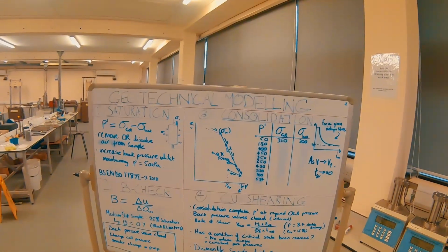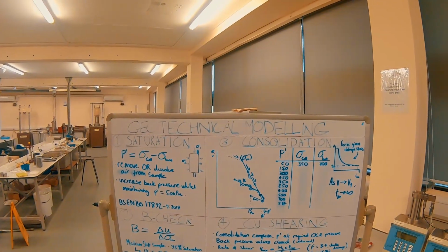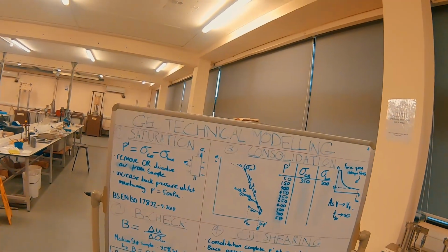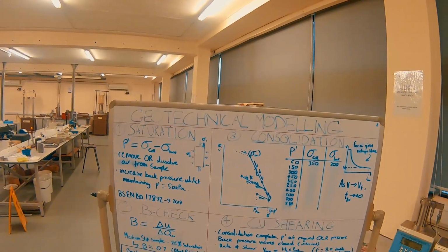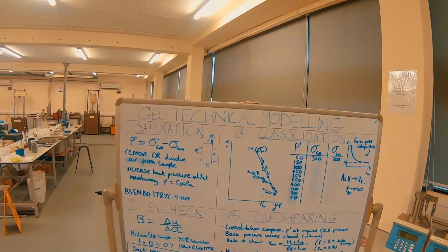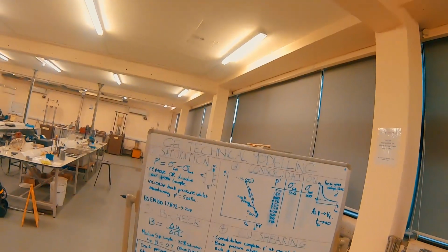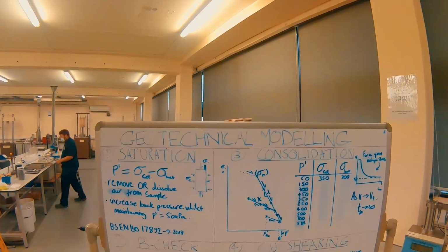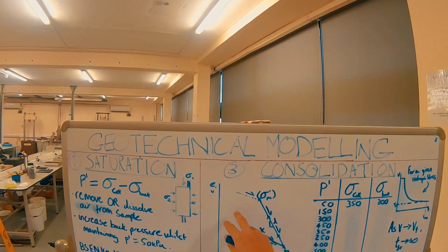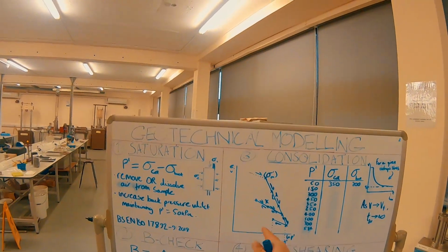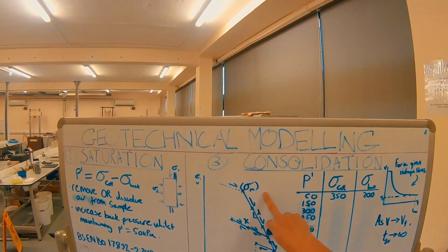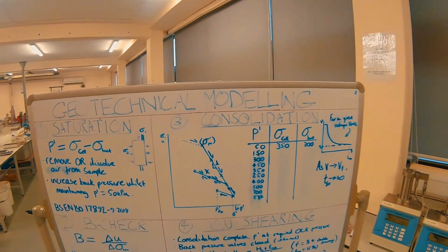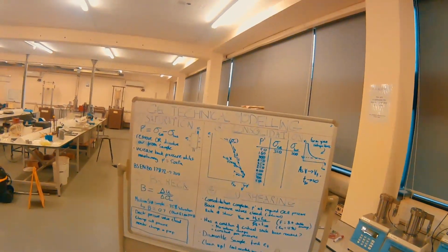So thinking in terms of our CAM clay frameworks, we have a slightly different QP space with one-dimensional compression as we do in isotropic compression. So we want to move past this point fairly quickly and move on to our lambda line in isotropic compression.